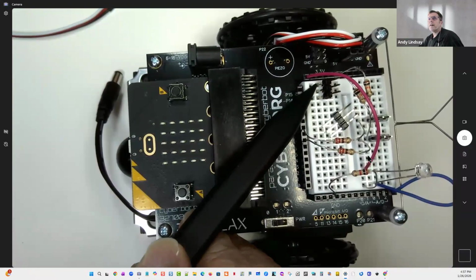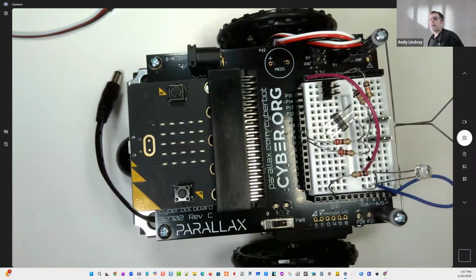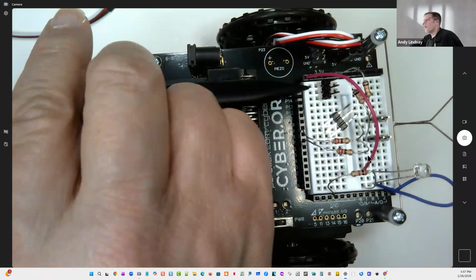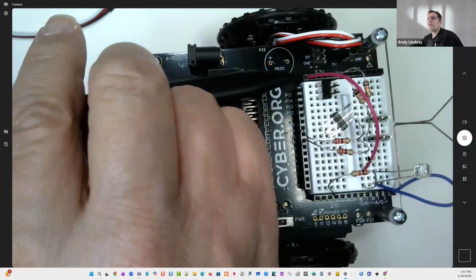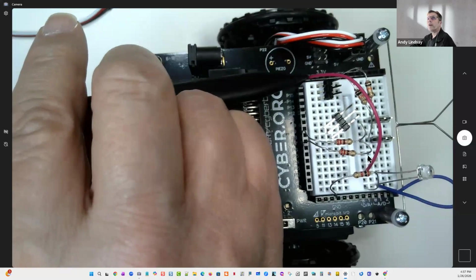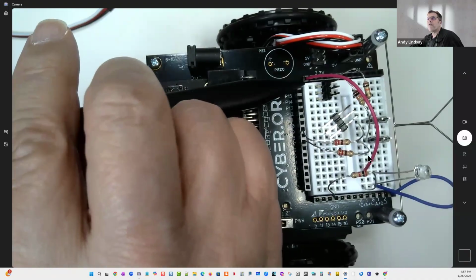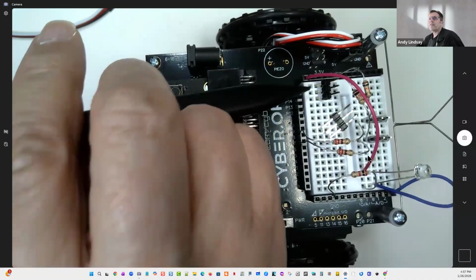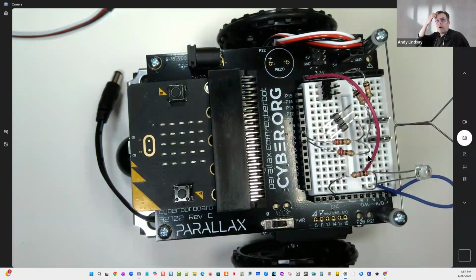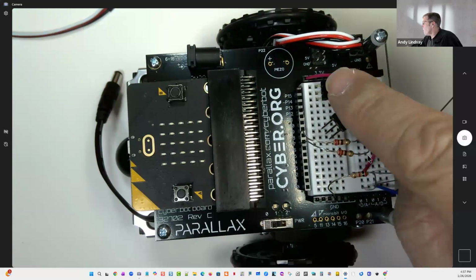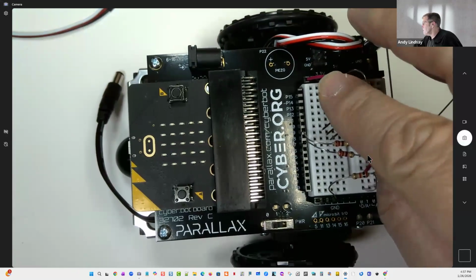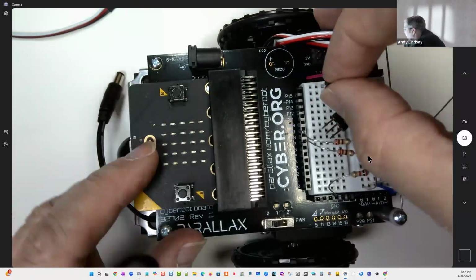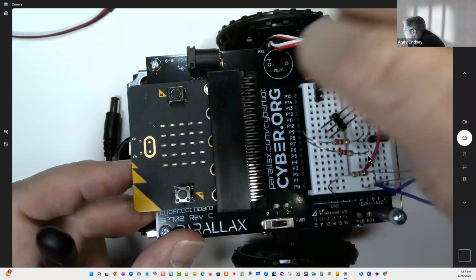And then I've got the QTIs started on the next column, at the top row of the white breadboard. So we do not want a pin going into this black 3.3 volt header. We just want 3 pins into the top row of the breadboard. And so once you've got that started, go ahead and press it all the way in.